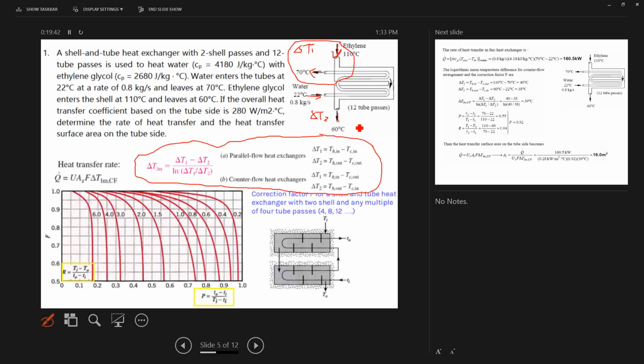That's something you are going to include in your lab report. Because in the lab report, as I mentioned, you need to do both parallel and counterflow and do the calculations for that. So I provide this as an example, which is counterflow. So for counterflow, the first equation we need would be UA delta T. If you are familiar with convection, you know it's just convective heat transfer, similar to hA delta T.